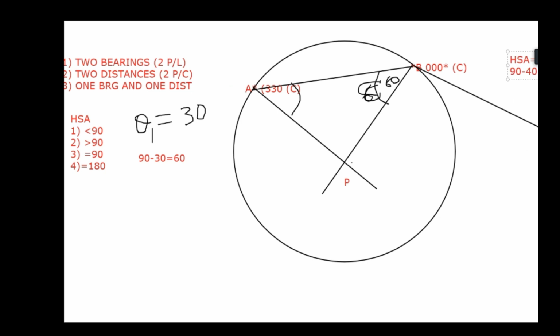Again we put the protractor at point B and draw 50 degrees. From C also, I draw another angle of 50 degrees. Both angles are 50, and we get another center Q. With respect to Q, QC and QB will be your radius. These angles will be 50 and 50.